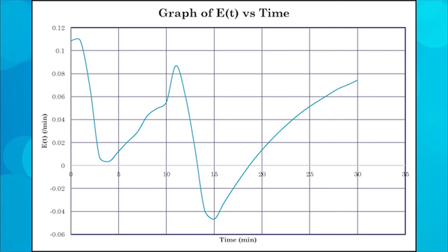The residence time distribution suddenly dropped to a minimum value when the pulse of tracer is injected suddenly for 2 minutes. The sudden increase in concentration results in a lower time span of the tracer in reactor 3 for both pulse inputs. The stagnation zone reduces the effective volume of the reactor, which leads to the decrease in RTD. The RTD will then increase over time until it reaches a steady state value.